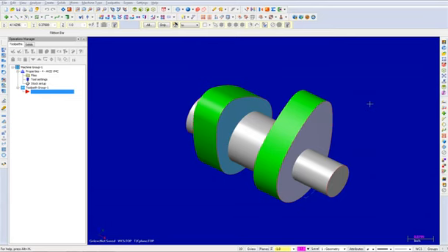In this video, we will create a rotary toolpath. A rotary toolpath is used on machines that allow simultaneous 4-axis movements to create a 4-axis surface machining toolpath, which cuts around or along the axis of rotation on the machine. In this case, we're using the x-axis. The rotary toolpath is a finish toolpath.